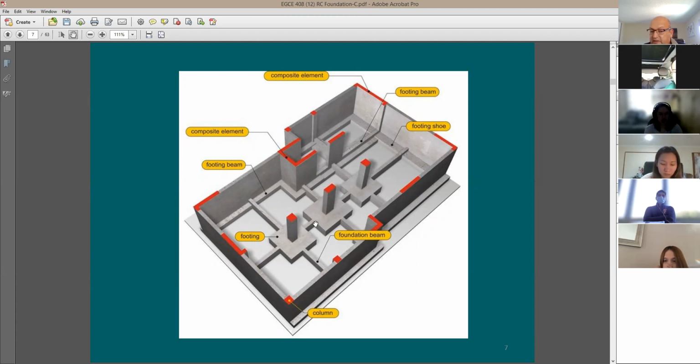These beams. You see these beams running across? These 4 beams are to control this footing and be sure it's not going to be shifted right or left during the service life of the building. So these beams actually just control the formation and the location of this pad. So we don't want it to start to shift right or left. We don't want it to settle more than what we're going to be allowed to settle.